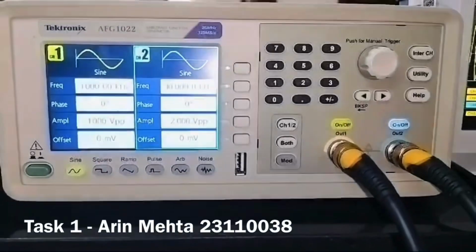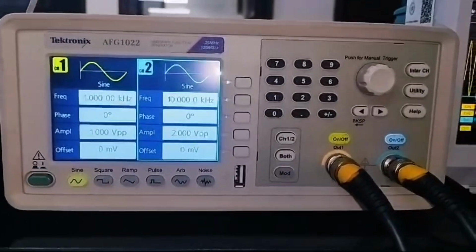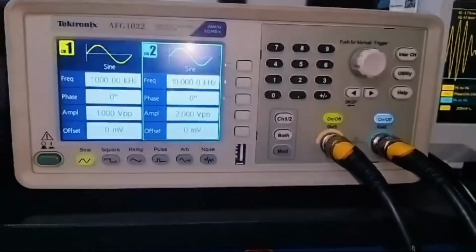Hello, I'm Arun Mehta. I'll start with the explanation of implementing an analog multiplier circuit using a TI analog circuit board to multiply two sinusoidal waves. So this is the signal generator. We have two input waves, both are sine waves. One is 1 voltage peak to peak and 1 kilohertz frequency. The other is 2 voltage peak to peak and 10 kilohertz frequency.